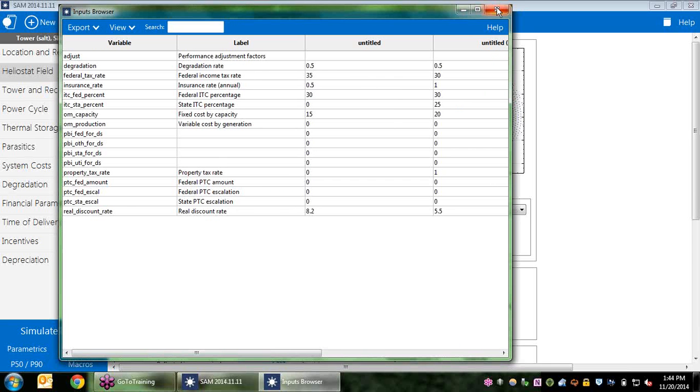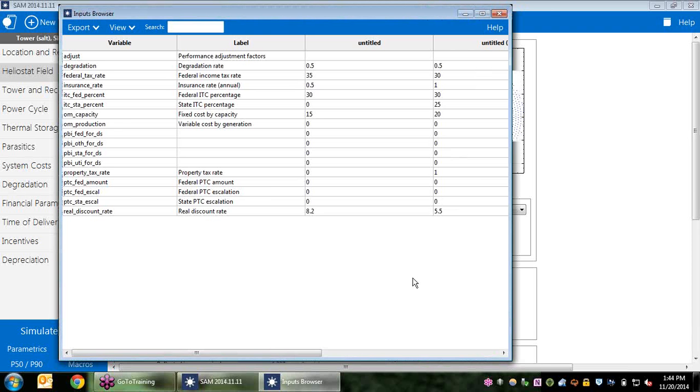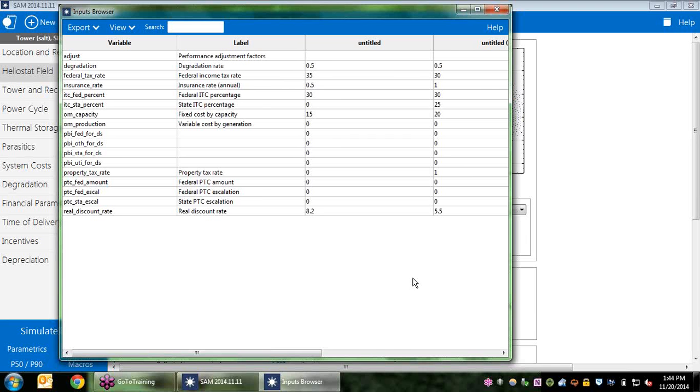Some variables listed as required are not shown. There are some variables in SSC that are required to run a module that are not changeable in the user interface, so they're required basically just from a programming standpoint. So it may be that if you're accessing SSC directly through scripting or something else, that you are running into variables that are not present in the user interface because they're set behind the scenes. So I would recommend that for those particular variables, if you have questions, to contact SAM support. Make sure you use SSC dev. And make sure that you are using SSC dev is a good point.